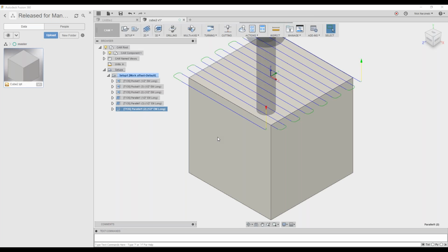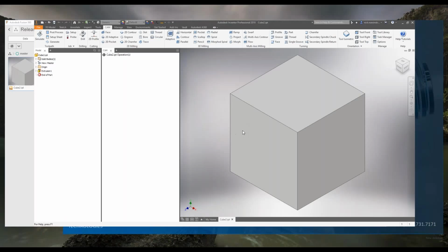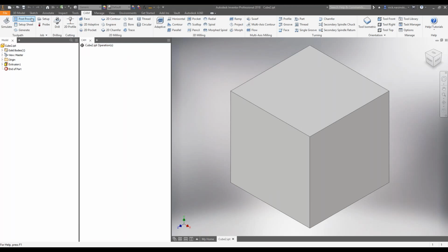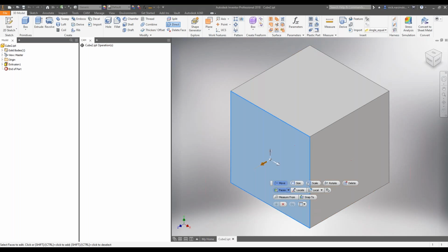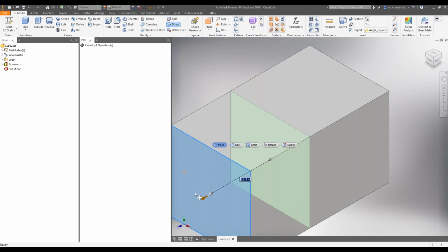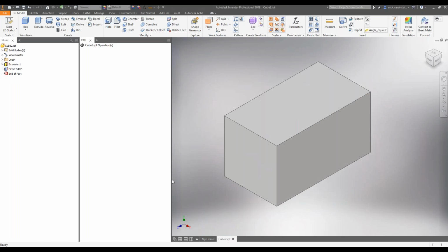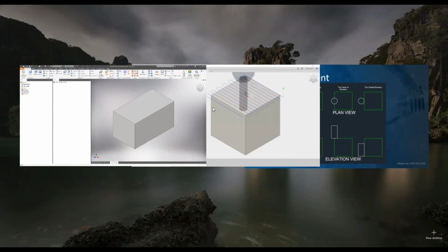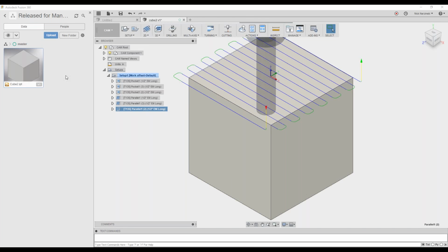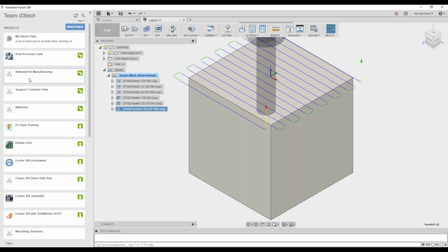All right. Oh, and so with AnyCAD, if I come back to Inventor, just for instance, just so you guys can see this, let's just throw a direct edit on here and move that face a certain distance, say okay, save that file. If I jump back to Fusion now, it might take a second here. So let me go to the right folder.